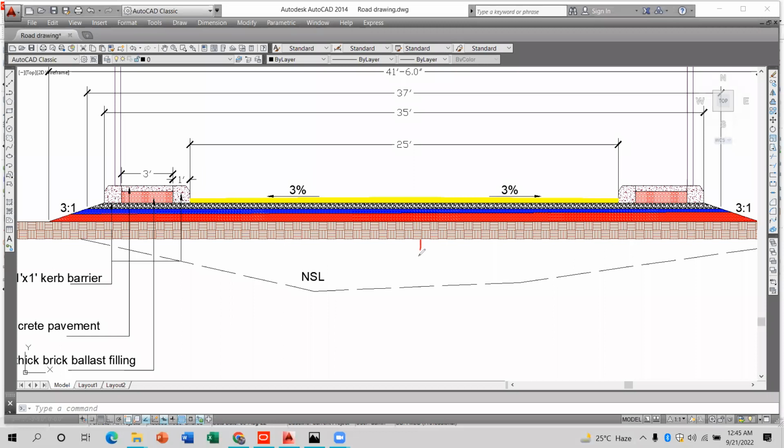After the natural ground compaction, as you know, there is a lot of filling here, because we have to reach the level of the road, but at this time we lie very much below the road. Therefore, in order to achieve this value, we have to fill it. For the fill, there are different criteria in the road. There are actually three types of zone here. The first one is the A class zone, that is included in the substructure. The other one is the B zone, that is below the subgrade and sub-bottom, and the third one is the C zone. Remember that the C zone always has unlimited layers.